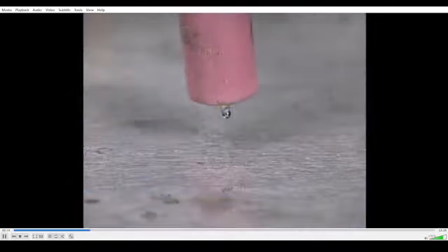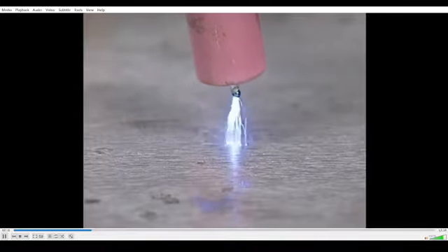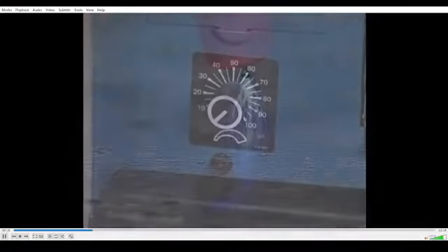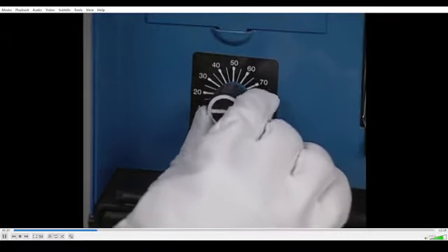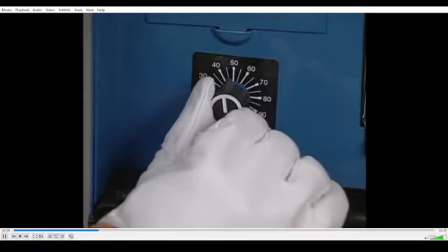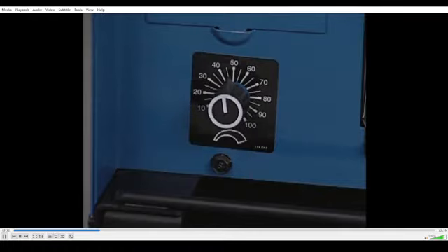High frequency assists with arc starting by creating a path from the electrode to the work. Some machines have a high frequency intensity control. The intensity control regulates the amount of high frequency in the same way that a volume control on a radio controls loudness. Typically, the intensity control is set about midway between the high and low values.